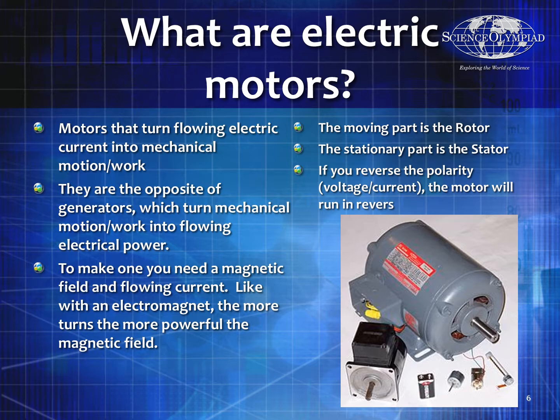For a DC motor, if I reverse the polarity, I'll reverse the current and I'll reverse the direction of the motor. Another thing to keep in mind is that a generator works exactly the same way. You provide the mechanical force to spin the rotor around, which then induces a current. For a lot of DC motors and AC motors, if you turn the rotor by hand, or put it up against a steam turbine or something like that, that's how you generate power.